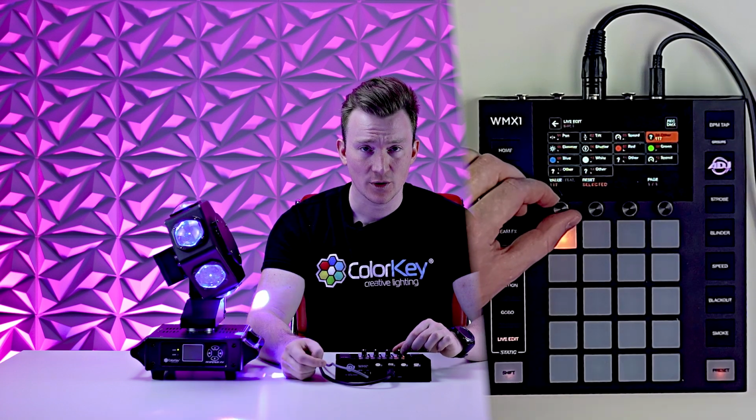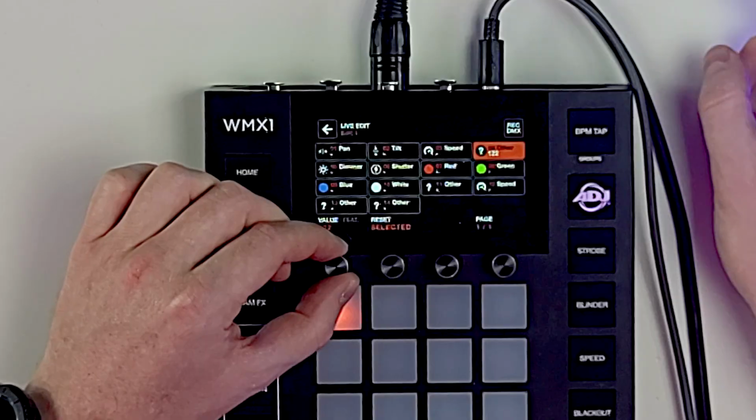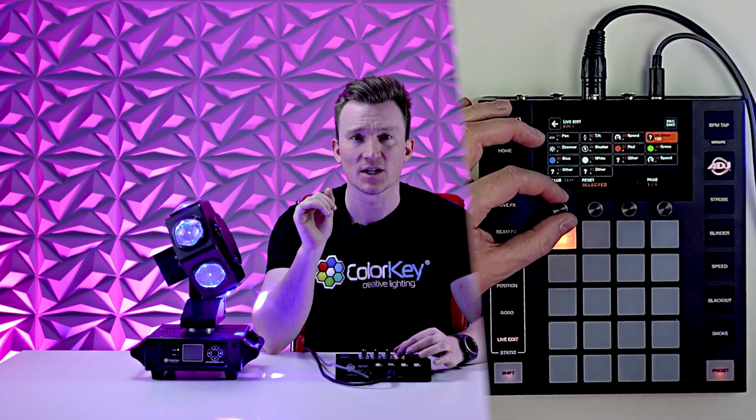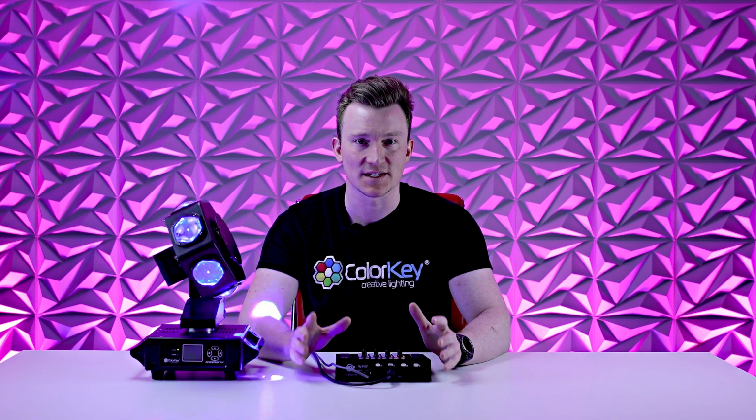As I increase the value, I can select different positions. So channels 0 through 127 are static positions for our Z motor, but as soon as I get to 128, you'll notice that we are in a clockwise rotation going pretty fast. If we want to slow that down, we just increase the value a little bit more, and you can now see that we have a slower clockwise rotation. This is what I recommend. Let's set up a few different speeds so we can assign those to different looks.